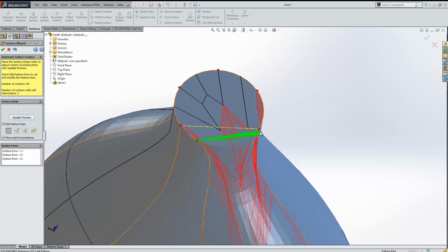If we put one over there, and we'll join that up. Now you can see I've got this line here. In order to add a feature point, you need to go from a new point to an existing point. So now I've finished with that, I can actually delete that line. Highlight it and delete it and remove it because I don't need it anymore.